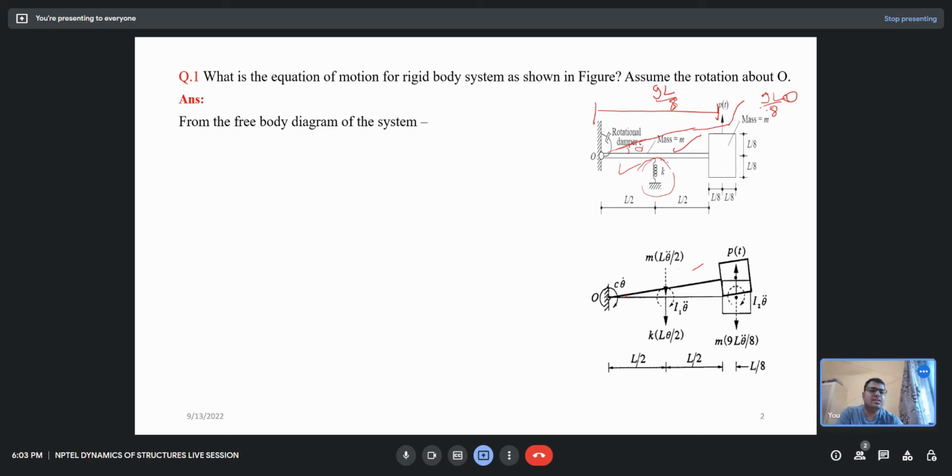If I displace this bar by theta, this mass also tries to rotate. To resist this, there is an inertial force due to the rotation of this mass block about the center of the block. That will be m theta double dot.